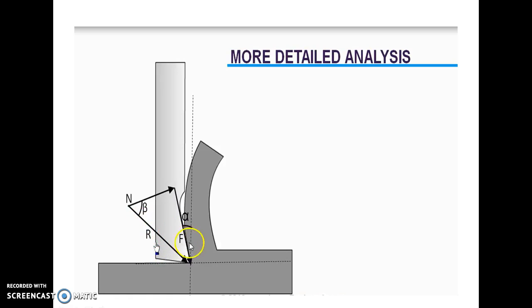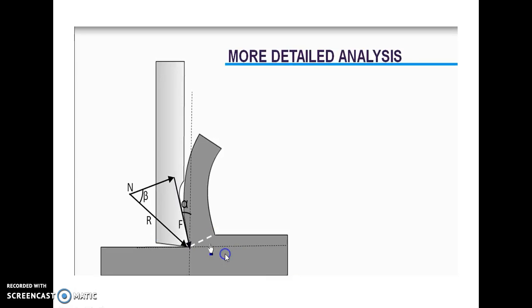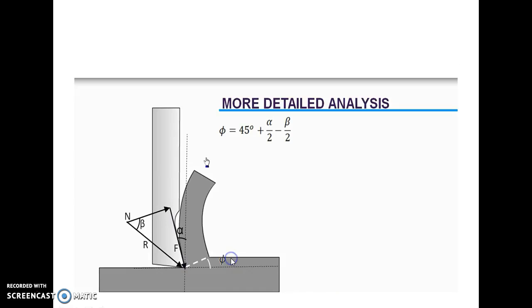And what are the other forces acting on the chip? You can see some metal thickness increase from the uncut side to the cut side. This thickness increase is due to interplanar slip between different metal layers, and there should be a shear force to support that. For simplifying our analysis, we are assuming that this shearing action happens on a single plane, exactly on this plane.